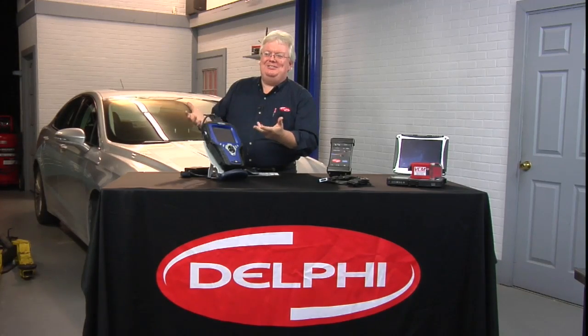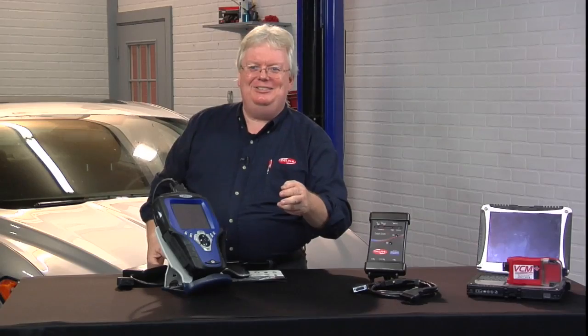Or if it's in a Chrysler, you may see the low-speed bus talk to a module on the high-speed bus called a TIPM, totally integrated power module under the hood, and that is your gateway to talk through a dedicated bus. Mercedes does the same thing through pins 6 and 14 to the DLC, called Diagnostic CAN C.